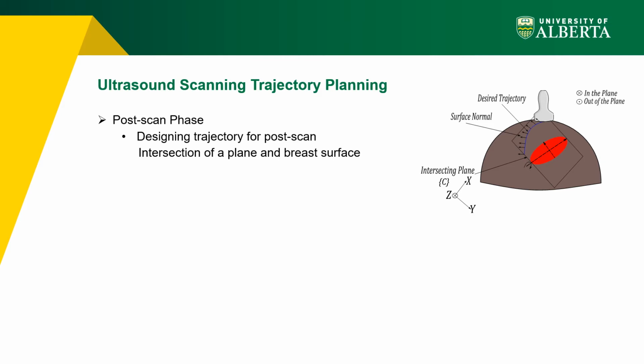The geometrical information of the ellipsoid calculated in the pre-scan phase is being used for calculating desired value of in-plane and out-of-plane rotation and XYZ position of the probe. We define orientation in axial plane as in-plane rotation, and the orientation out of this plane as out-of-plane rotation. The in-plane rotation and the movement of the probe in the z direction of base frame is being updated in